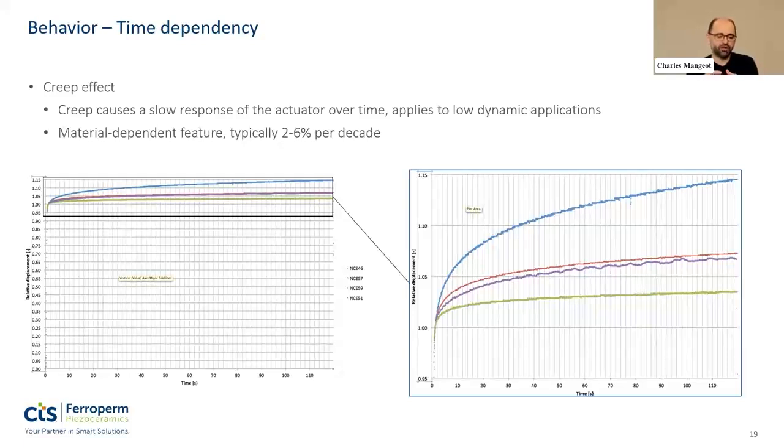So you may not have all the information from a manufacturer, for example. But yes, there are some models to calculate displacement from charge. If you have a brand new material and you just use it for the first time and measure displacement and charge at the same time, you might be able to get a relatively good fit between the two.